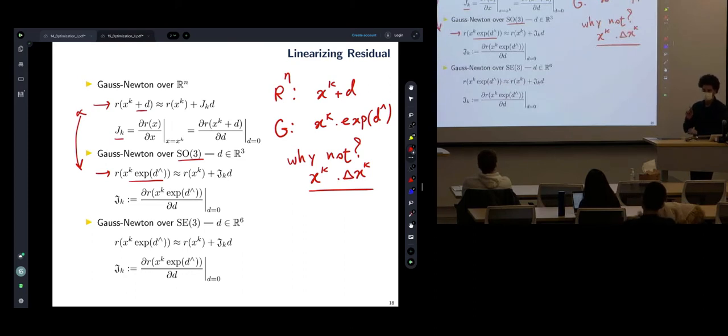However, the main reason is that we want to use linear algebra, and that's the style of Gauss-Newton. We're not going to be able to use it if we're working with nonlinear pose and rotation. That's the same reason in the invariant EKF, we are tracking the covariance in the Lie algebra. Innovation is in the Lie algebra because ultimately it's a vector space and we can use linear algebra to manipulate terms.